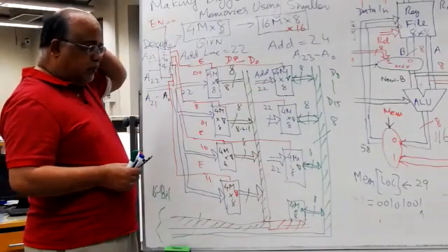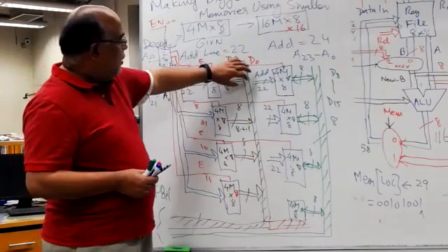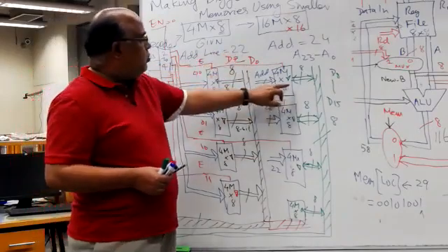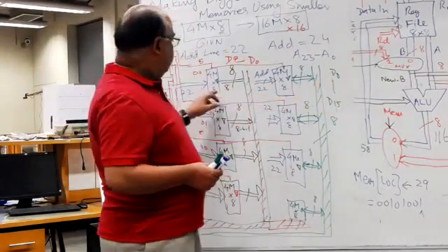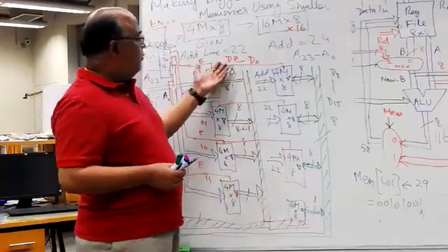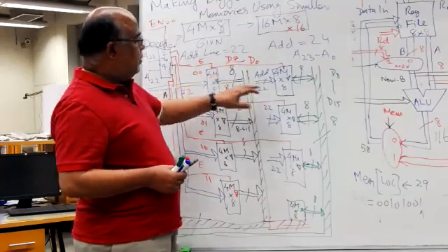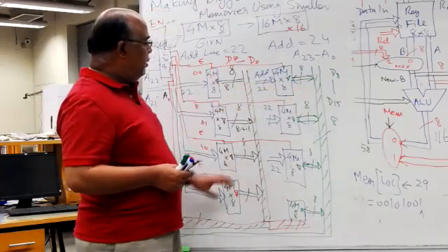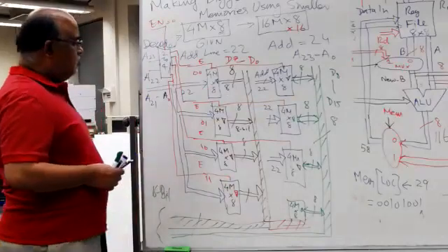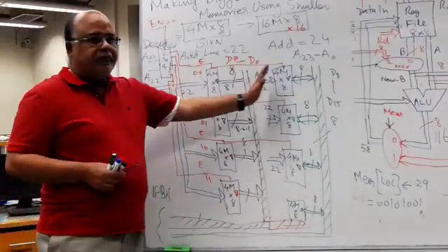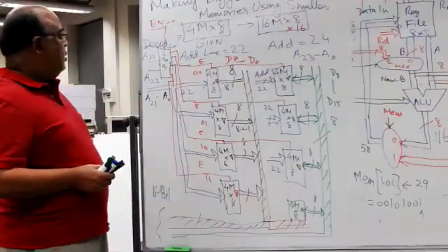So you will notice that in a memory range the address lines are the same for all; only the data lines are named differently. This one is D0 to D7, but externally they are named D8 to D15. So D0 to D7 from here, D8 to D15 from here, total D0 to D15, a 16-bit data bus. So you now have a horizontal expansion and a vertical expansion. Both of them are there.